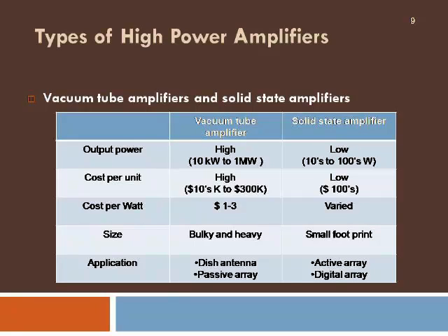In most cases it's not the cost or the power output that decides; the size also matters. Vacuum tube devices used in a radar are very bulky and heavy. Whereas if we go for a solid state amplifier like a GaN amplifier or other types, it is very small in size and the weight is minimal. So whenever we consider portable radar systems, we can easily consider solid state amplifiers as a good candidate.